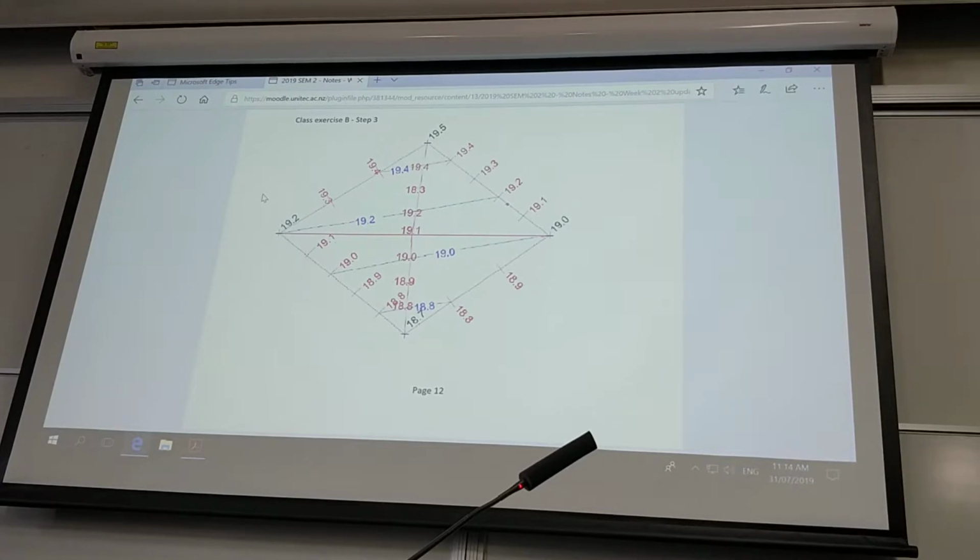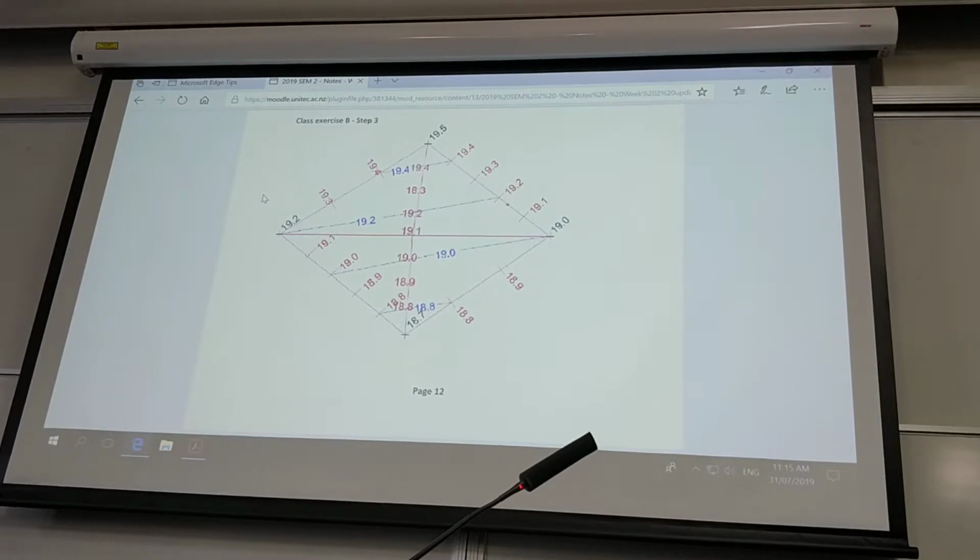Even if you have got a friend who witnessed it and you've got a YouTube video that you did it all perfectly, I will not be giving anyone 2 marks unless they leave their lines on here and some sort of indication of where the calculation came from. I would like you to freeze that in the background, so I only want to see the contour, but then I'll go for the layer that you've got it on. So the layer should be something logical, like triangle, contour mark, something like that, and just freeze it. You can call the layer frozen contour, frozen mark or something. It's up to you. But I'll see it there. I'll thaw it. I'll have a look. I'll put my template on top, and as long as everything's pretty close, you'll be getting marked.